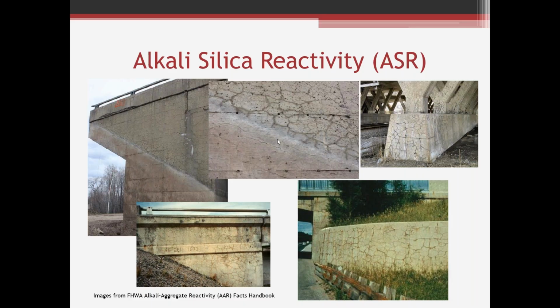And here's a picture of that interface. There's a little bit of cracking here, but certainly not as much as where all that wetting and drying is occurring. So again, keeping the water out is probably the most effective way. Well, the most effective way is to make sure that you've got aggregates that aren't susceptible to ASR. But once you've got it, it's hard to deal with a lot of times.